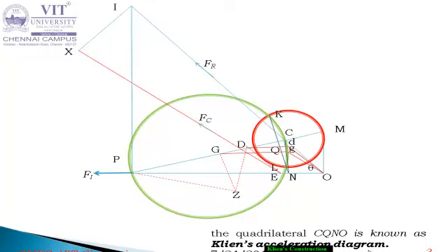But Fi, where the connecting rod weight is acting at G. So you have to consider this weight also. Weight of the connecting rod is acting at point G. So this is W. From the W there will be some component acting upper side. So draw one perpendicular line, at a right angle to this line, from I. Both will intersect at Y. So that is the point of intersection. Now all the components we have included.